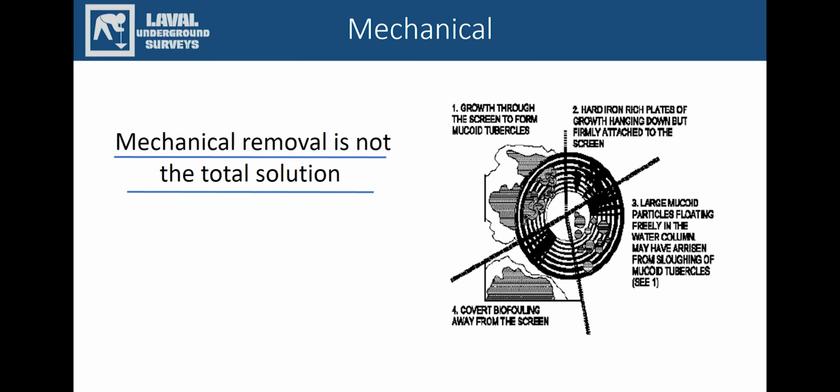The picture on the right shows where biofouling, in the dark gray color, can occur. Using solely mechanical efforts won't treat the further outside of the well screen, and using solely chemicals without proper agitation will leave those same places mostly untouched. Combined efforts of mechanical and chemical treatments can get you the best clean.